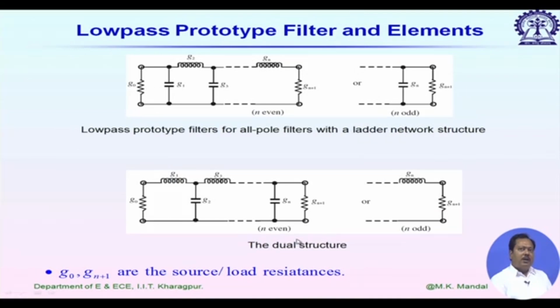So, next, how to realize these functions. We start with low pass prototype. If I ask you to design a low pass filter using lumped elements like capacitors or inductors, how will we connect them? Capacitors we usually use in shunt configuration, so high frequency components will pass through the capacitor, and inductors we use in series configuration, so they will attenuate high frequency components.